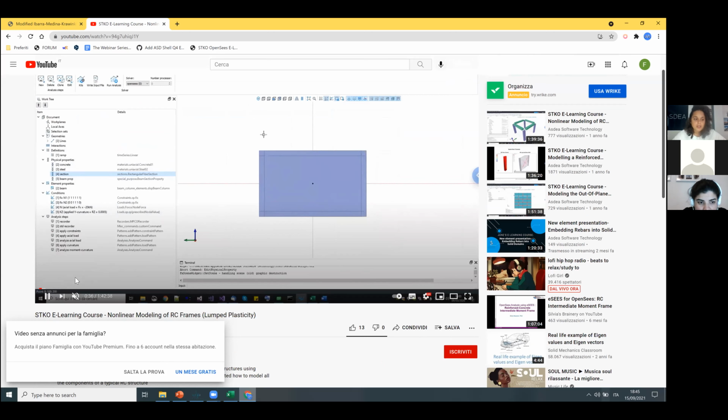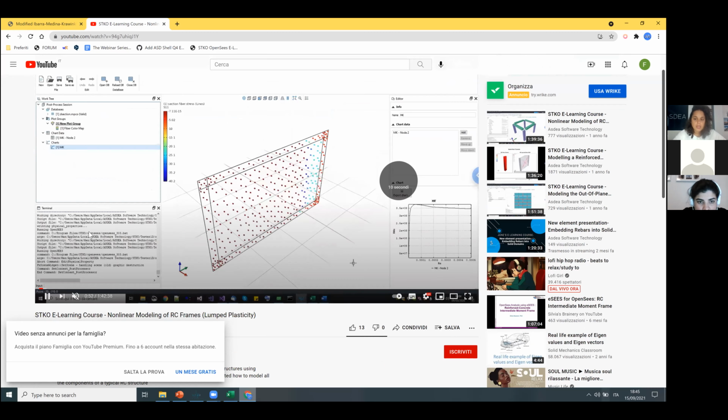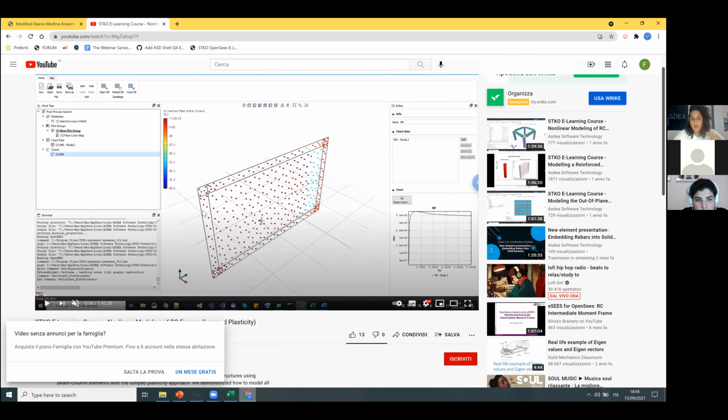And then in this, I'm just going to go a bit forward. Yeah, you see, he's just extracting the result because it has one integration point, so one fiber section. And from here he is extracting this moment curvature response. So you can either do this or have a column of a length that you know, and you can scale it up to your big model. But also if your column is 1 meter, it should work the same.